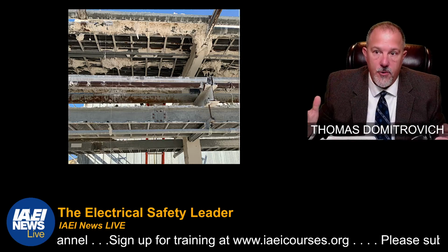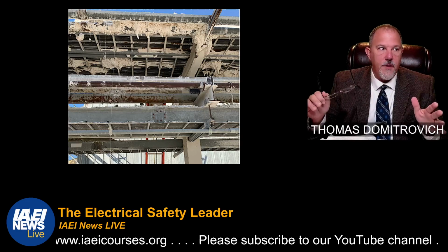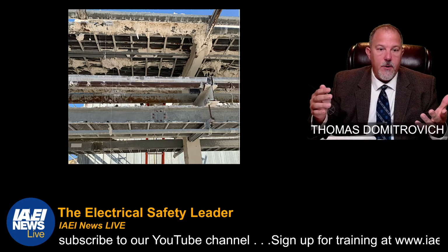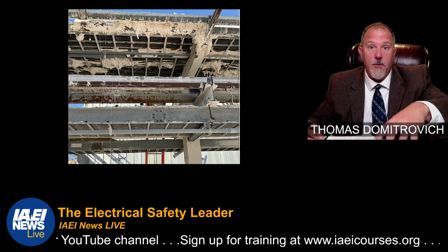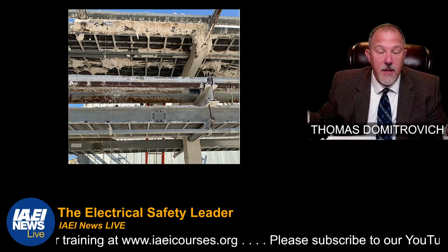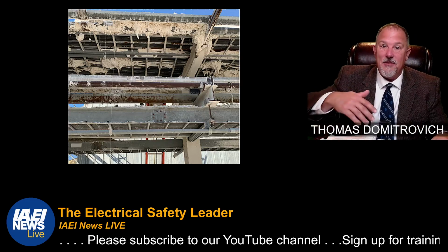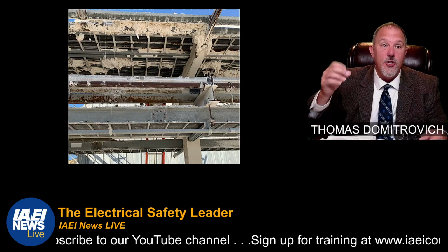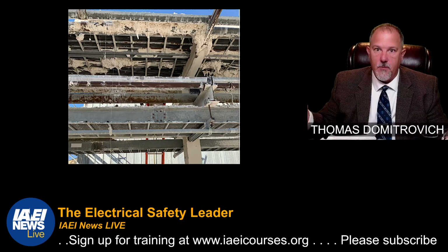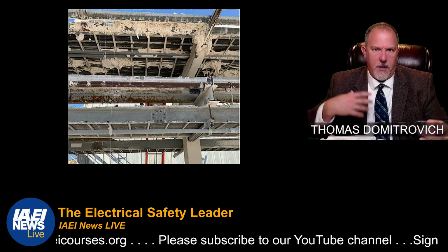So you think about chemical corrosion. When does chemical corrosion take place? It's when metal comes in direct contact with some corrosive material, solutions, whatever. So the concentration level of the chemicals, it could be in air, could be in liquid, mists. The duration could be an all-day type of thing, 7 days a week, 24 hours a day, 365 a year, or it could be very short durations periodically. And then the temperature plays a role as well. So for any degradation, those are some of the things you need to think about.